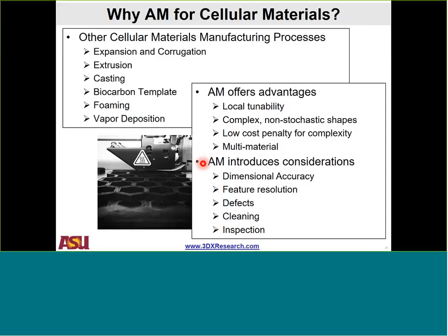But then, with additive comes considerations, and many of these are not specific to cellular. All of these are not specific to cellular, but some of these become more particular or sensitive when you deal with cellular materials. And these are the ones that I'm highlighting here: dimensional accuracy, feature resolution, defects, cleaning, and inspection. And I've got one slide on each of these, and I'm not going to do it justice at all, but I just want to touch upon each of these 5 points.